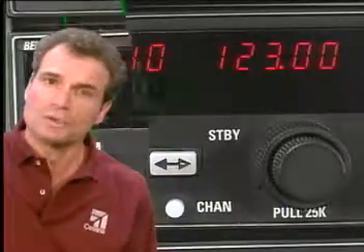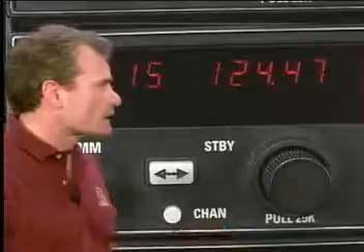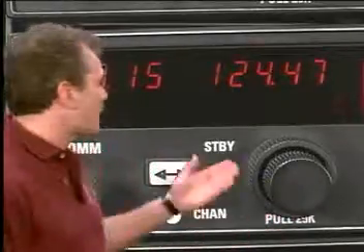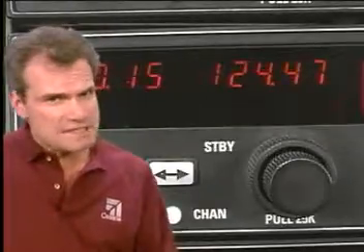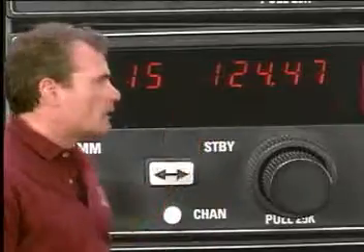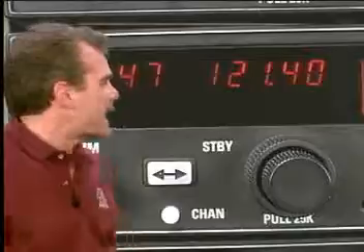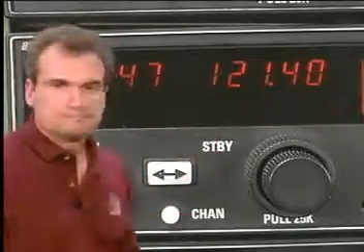In COM 2, you might enter Jacksonville's AWOS frequency 124.475. At a towered airport, you might even enter the ATIS frequency instead of the AWOS. For the standby, if it's a towered airport, you might put ground control in. Now in this case, you might put Wilmington Approach in here as a backup to COM 1.